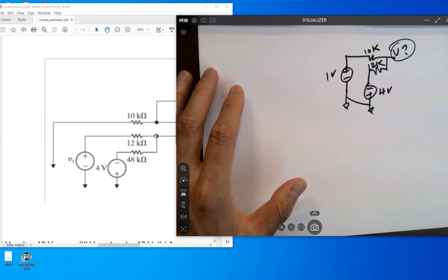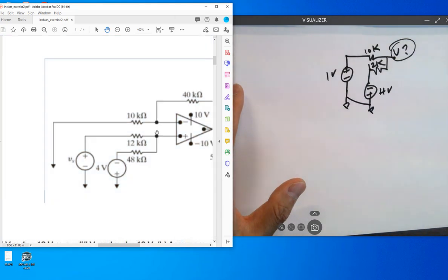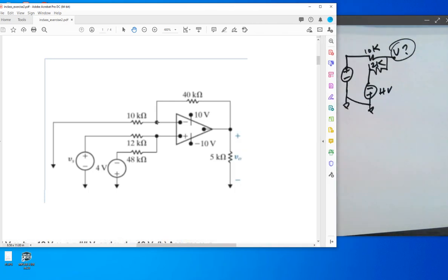So if you get that voltage here, and you know the voltage is being measured to this point, can you calculate V out from that point? What's the voltage here? 0, grounded, right? It's 0 volts. And then the voltage here, no current getting into the op amp, so no current over here. So basically the current flows from here, goes up, and reaches VL. Okay? So VL is over here, so basically it's whatever voltage you calculate from here, minus VL over 40K equals 0 minus this voltage divided by 10K.